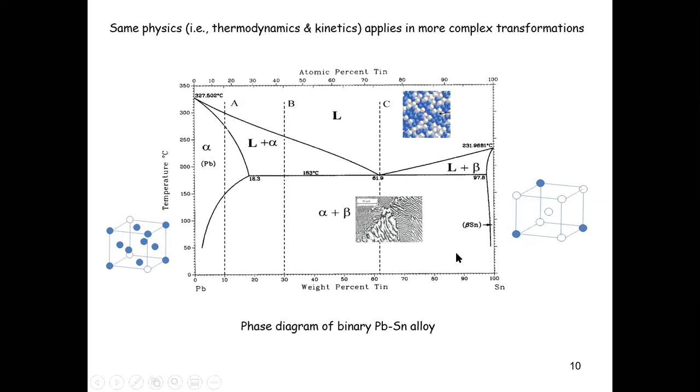So the alpha phase is what we call the lead-rich phase, and the beta phase, as you can see from the composition, is the tin-rich phase. Does it make sense to everyone? Now, based on this, I have two particles of two different colors, blue and white. Which color indicates the lead particle and which indicates the tin particle? The blue is lead, because in this case this is lead rich and we have more blue here, and this is tin rich and we have more white, or empty, here, right? So the blue represents the lead and the white represents the tin.